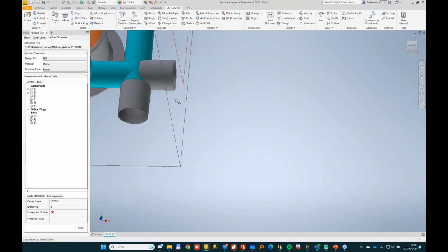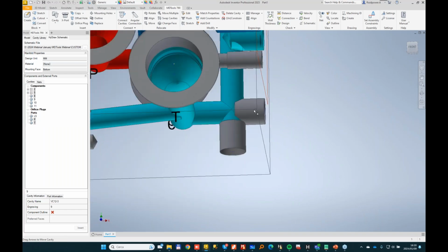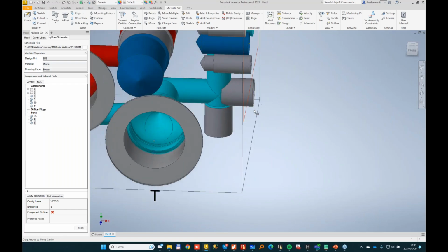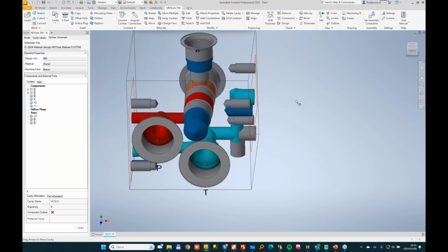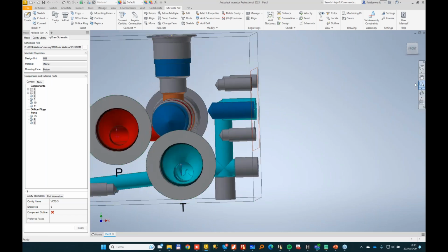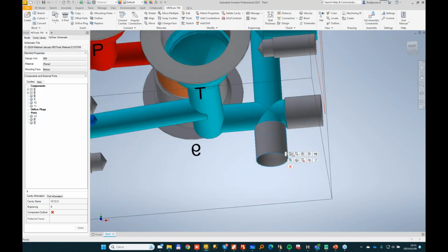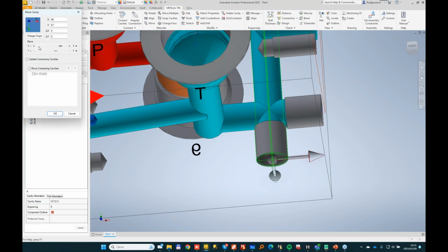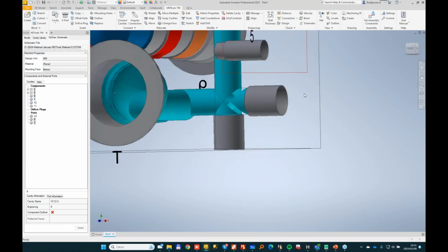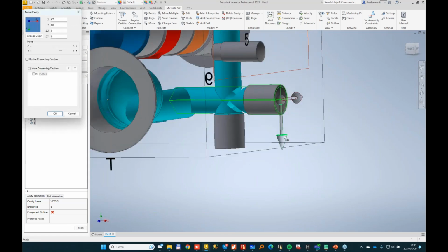So like in this case, this is not good at all because it will not be possible to fit this expander. So I'll add some material here. So I stretch my face and do a 105 millimeter. When you stretch material, the block, the drills will change in length, and again, like in this case, it's better to add a few millimeters again, and also in this direction.